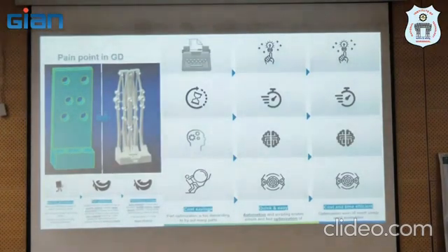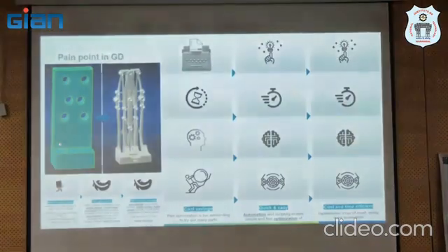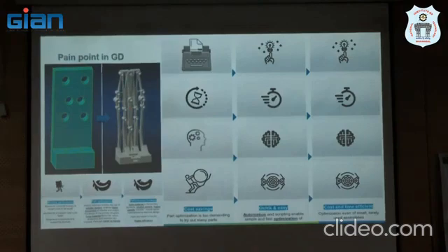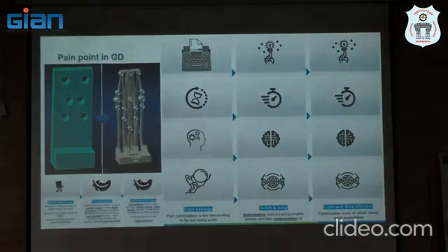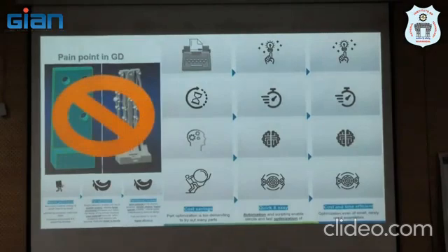What we are trying to say here is, when the design is very simple and can be conventionally manufactured, it makes no sense to put in all our effort and come up with a topology optimized design. This is not the right design, because the printing time and the complexity are higher than what it would be conventionally. So this shows that when we cannot justify from the design point of view, it is not recommended to use the 3D printing technique.